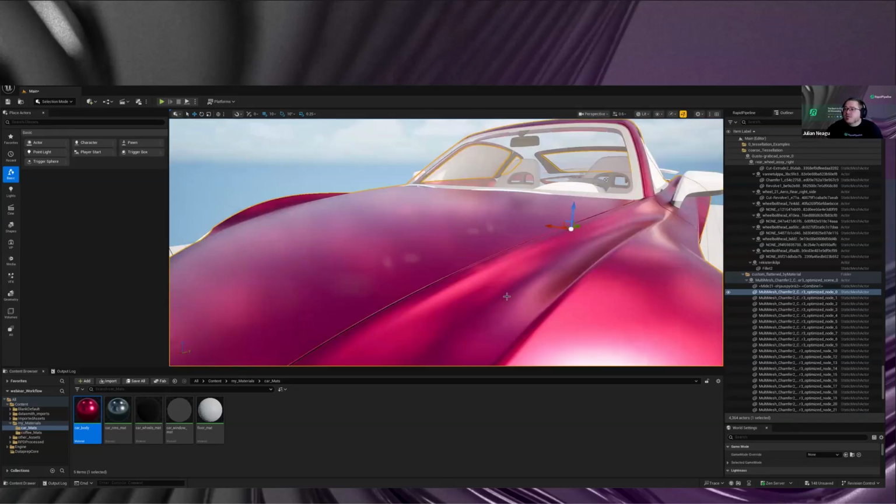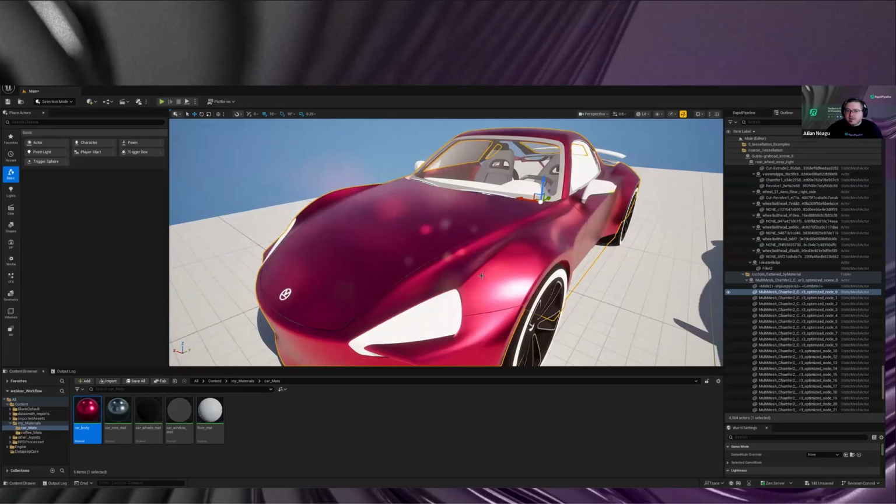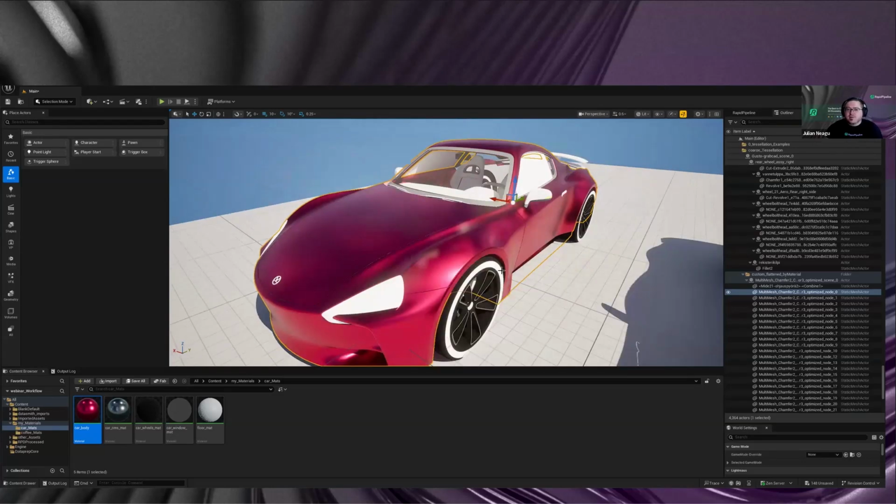Yes, the CAD kernel, exactly. It's not Parasolid, that's as much as I can say. It's a solid kernel which is running under other products as well on the tessellation side. What we did is translate the settings into a more human readable form in terms of surface deviation, and we're basically communicating with that tessellation backend. So it's not that we wrote everything on the tessellation side ourselves. There are a few things we wrote on top, but not the whole pipeline.